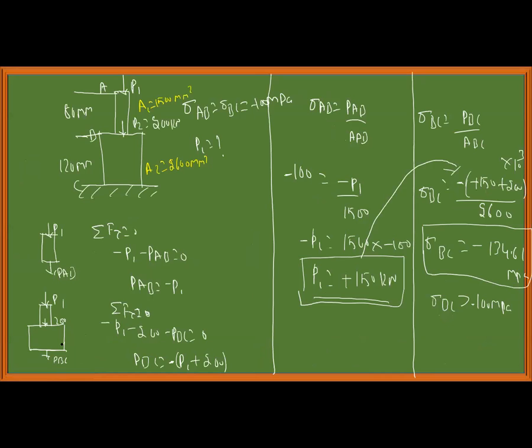and obtaining the value 150 kilonewton itself. This will not suffice. This is coming above 100 MPa, minus 134.61 MPa. But my structure is not designed to withstand that much load. It should be well within 100 MPa. So I have done like this. So this is the way. Have you understood? Yes, sir. Okay. Next problem, we'll go ahead.